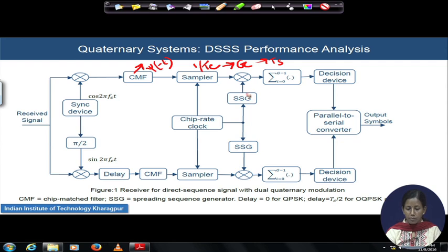Next comes the despreading section, where you have a multiplier followed by an adder, following the correlator architecture. As discussed in the earlier modules, the input to the adder circuit was Zi, and V is the combined signal after the addition and despreading, which enters the decision device.